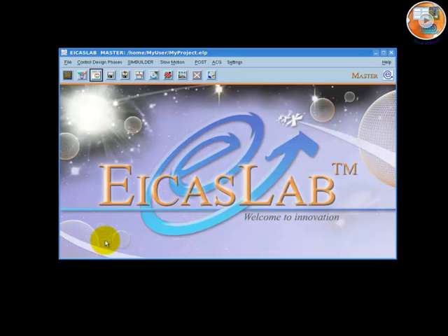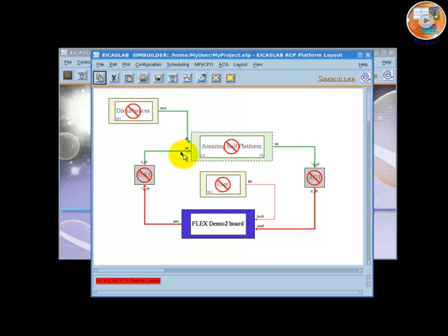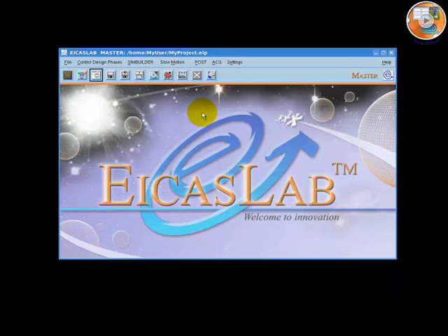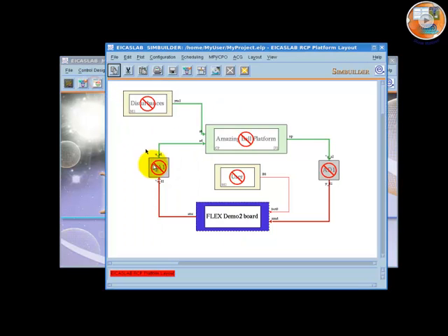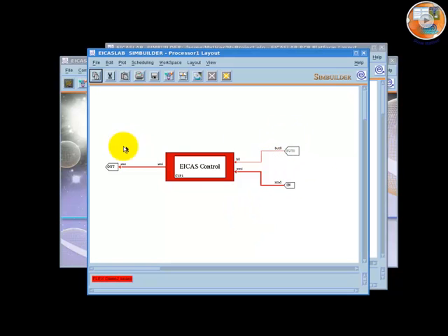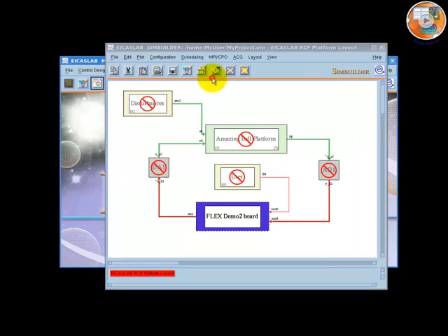In fact, starting from the set of recorded data, the slow motion works like a moviola, allowing the developer to process the plant input-output and the user commands recorded during the experimental trials, and to run the same control code executed on field for debugging step by step and variable by variable the developed control software. Summarizing, the slow motion takes care of recording the input and output data as they arrive at the RCP platform, that in this case is represented by the processor block.